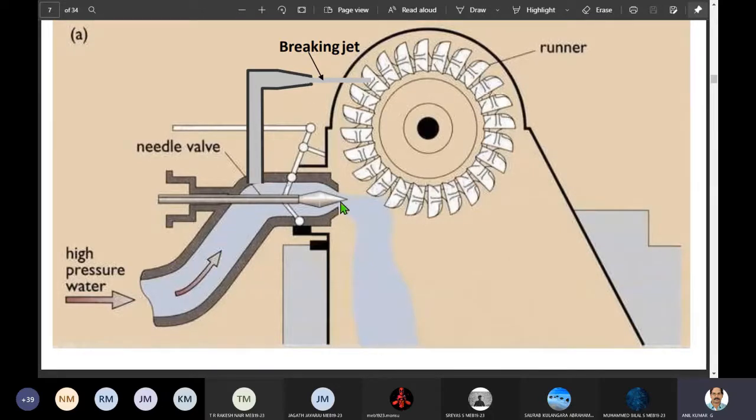So that's how the nozzle with spear valve arrangement completely converts the energy possessed by water into kinetic energy. So the moment the water jet comes in, throughout the turbine operation, the pressure will be atmospheric. See, air has access from below. This is open actually. There is a casing also. This casing has no hydraulic function to perform. It is not used for any type of energy conversion, and is just for avoiding splashing of water, to avoid such dangers. No hydraulic function.